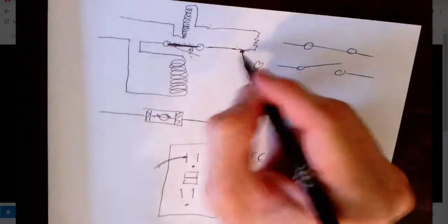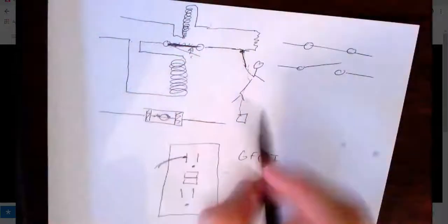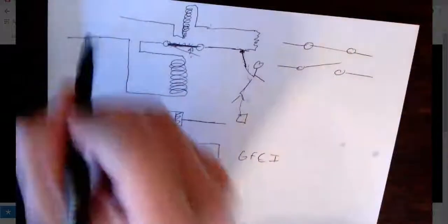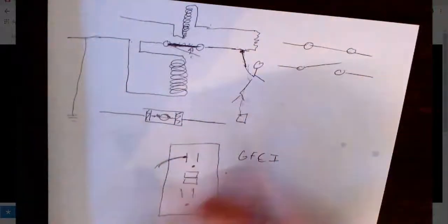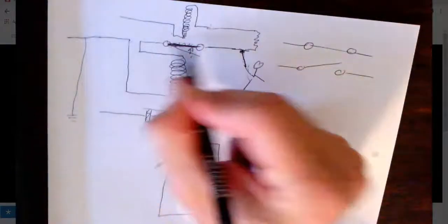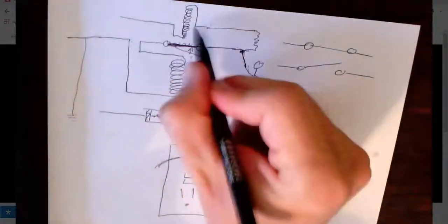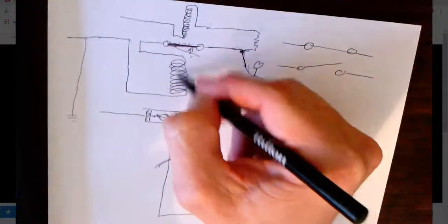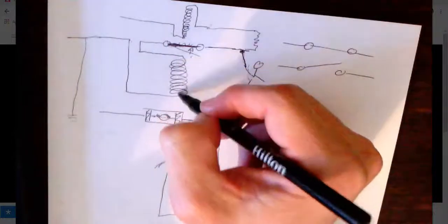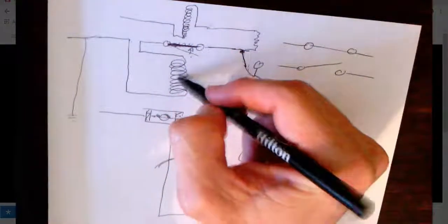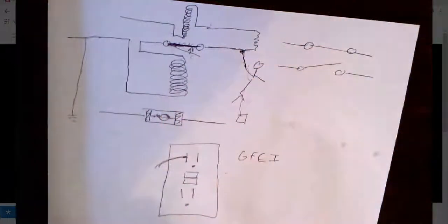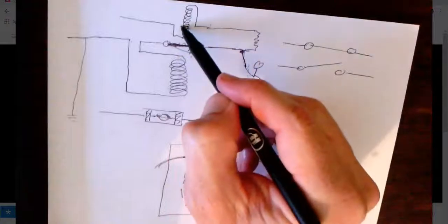and the ground is not a great conductor either. And how it gets back to the circuit is complicated. Back over here, there's a wire to the ground because of lightning bolts and stuff. But it could pass through you, pass through the ground, which is a bad conductor as well. But the idea here is this. This part of the circuit is getting electricity, and this part is not. So this will still be a magnet, at certain parts in the cycle of the electricity. This will be a magnet, and this is getting no current. So it's measuring these two currents, and if they're different, it pops open the switch. It's saying something is wrong in my circuit. The current over here should be the same as the current over here.